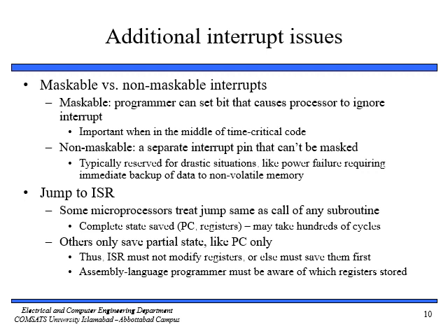Both of these are external interrupts. In a maskable interrupt, the programmer can set a bit that causes the processor to ignore the interrupt. So whenever we are using a maskable interrupt, it means that we can set a bit so the processor does not need to do something on the interrupt. It will simply ignore the interrupt.